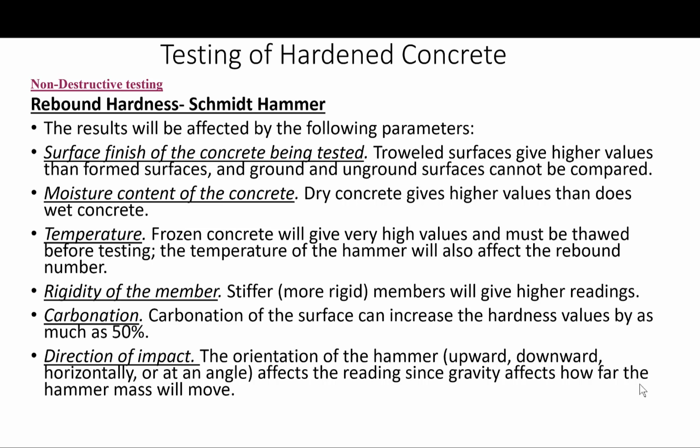So again, accuracy and thorough knowledge of this method is required for anybody to attempt using it and interpret the results. The general view held by many users of the Schmidt rebound hammer is that it is useful in checking the uniformity of concrete and in comparing one concrete against another, but that it can only be used to obtain a rough indication of the concrete strength in absolute terms.